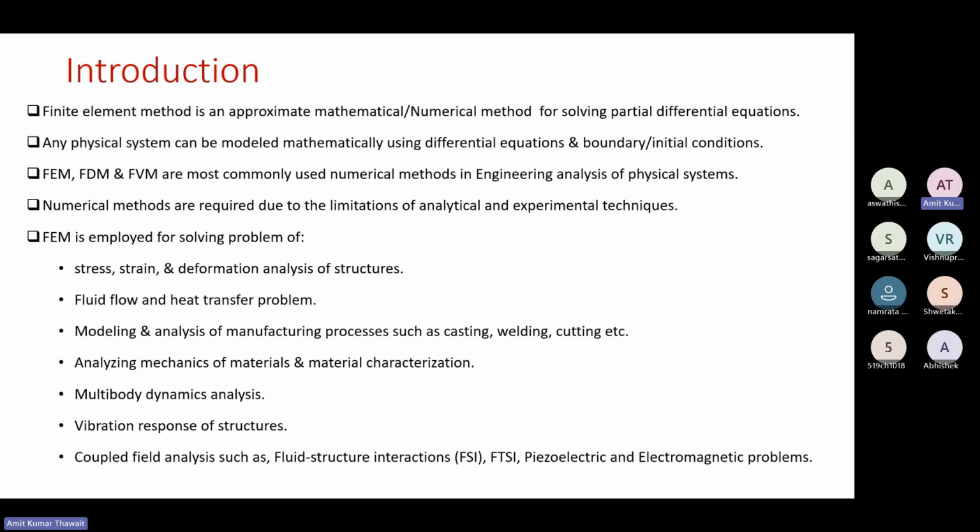Analytical and experimental methods have certain limitations, and to overcome that, we use numerical methods. The analytical method is very accurate, but it is limited to only simple problems, simple loading, simple boundary conditions, simple geometry. If we have any complex system, then we cannot perform analytical analysis.